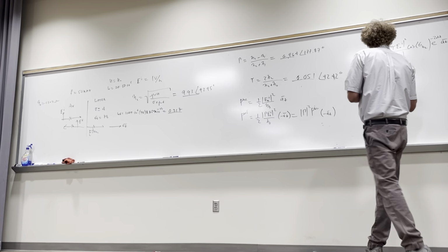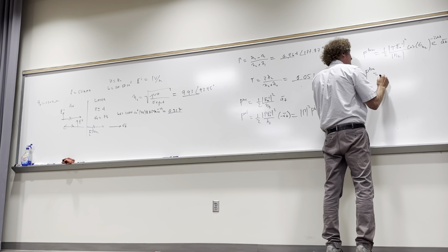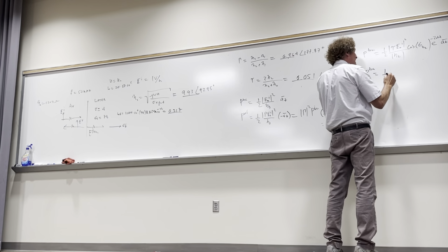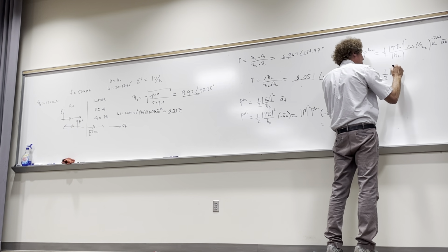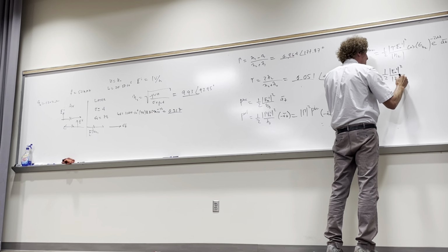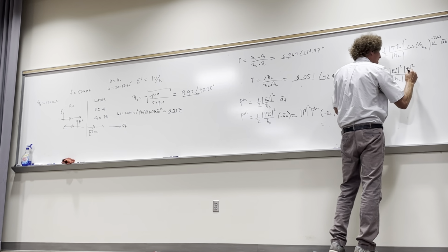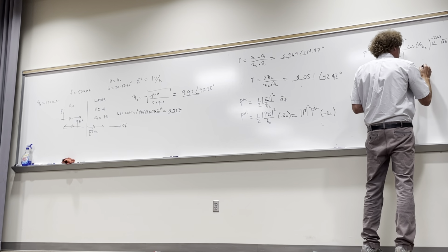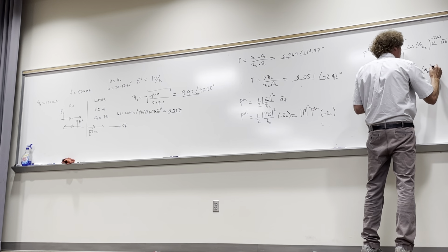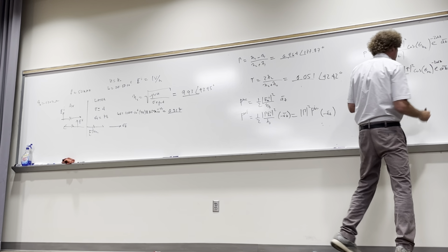All right, back to this thing. If you look at P transmitted, that's 1/2. Then I can get the magnitude of E naught incident here squared. It's over the magnitude of eta 2. Then it's the magnitude of tau squared, and then the cosine of the angle. And you can put e to the minus 2 alpha z if you want in the a_z direction.